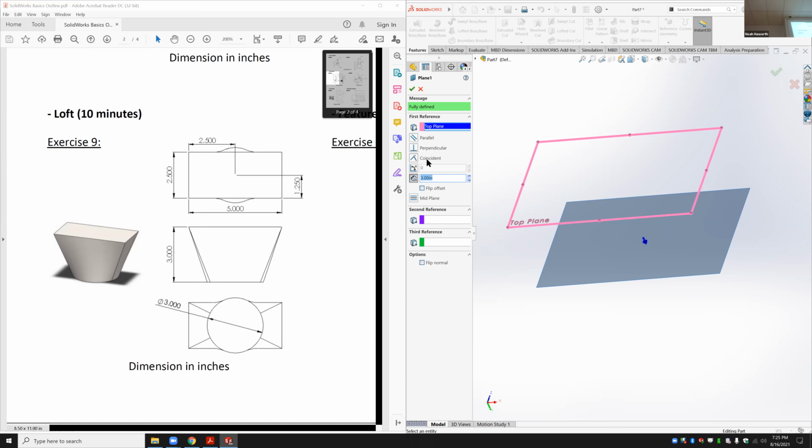And then for your offset distance. It doesn't matter if we use a center rectangle or corner rectangle or anything, as long as it lines up properly. You want the center of your rectangle and the center of your circle to be in line with each other. Not quite concentric, because a rectangle is not a circle, but you want their centers to be intersected by a normal axis, which is a mathematical way of saying that.